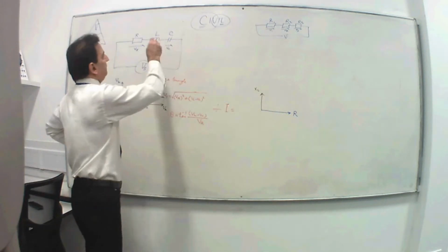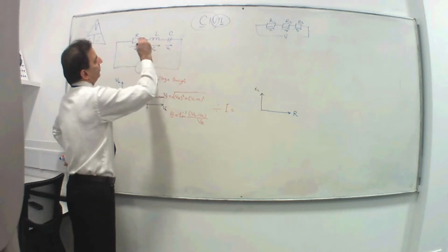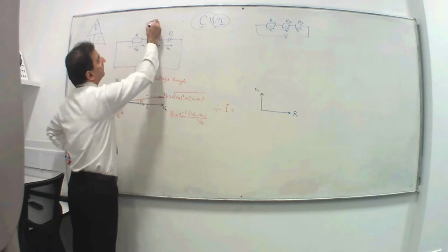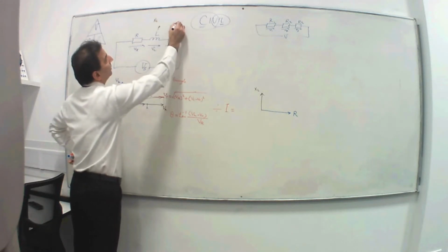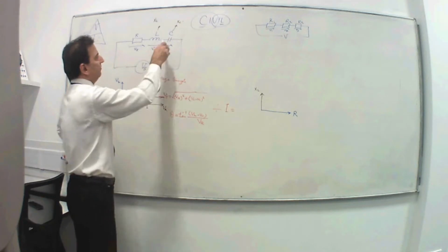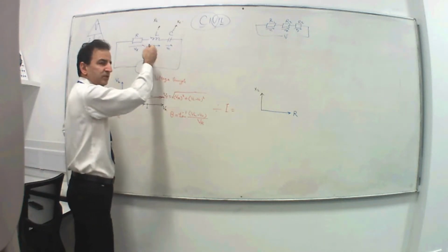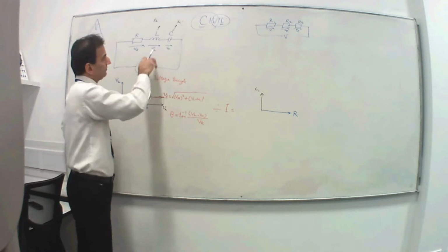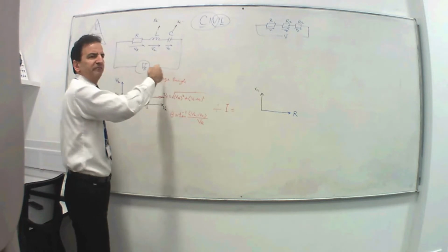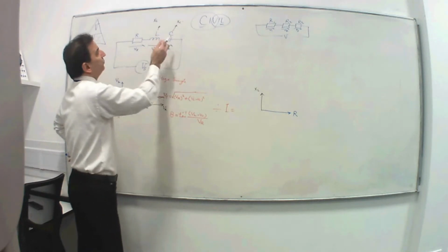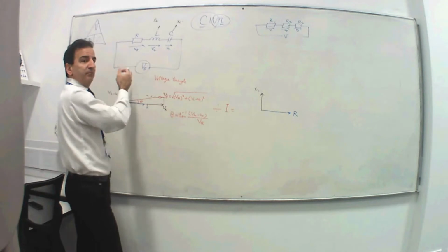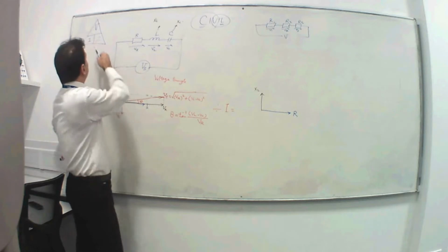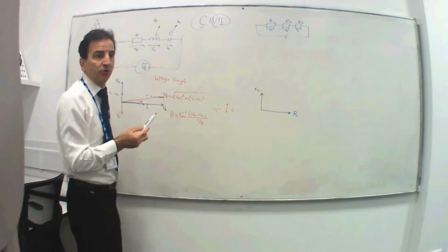Now, if you've been given L and C, you have to straight away convert that to XL, and this one to XC, because L is measured in henries, C is measured in farads, or multiples of them, millihenries, microfarads, and all that. So you have to convert them to a unit that is measured in ohms, similar to the rest of the circuit, because impedance is measured in ohms.